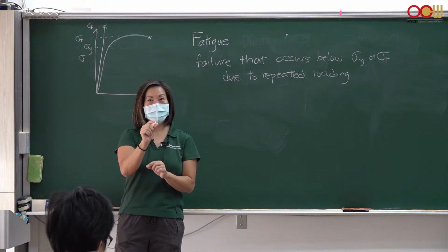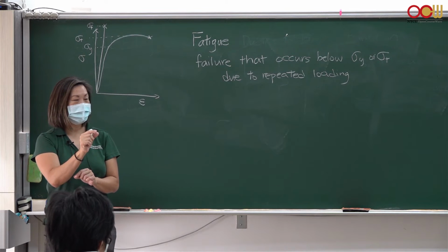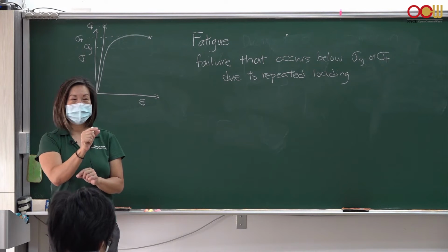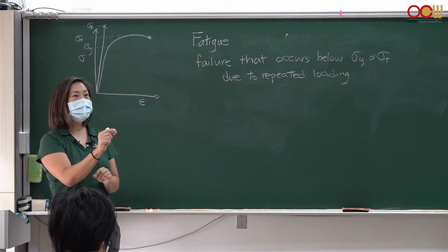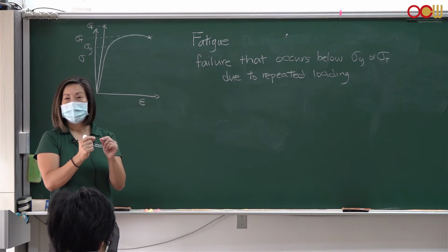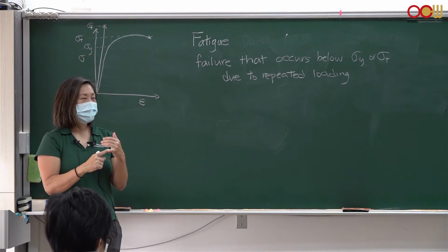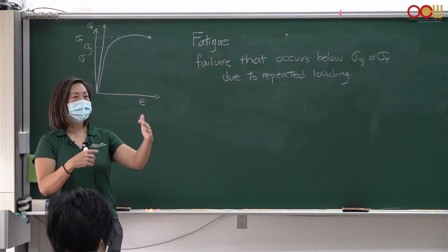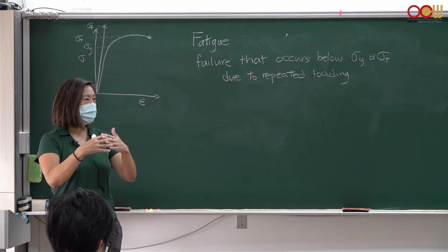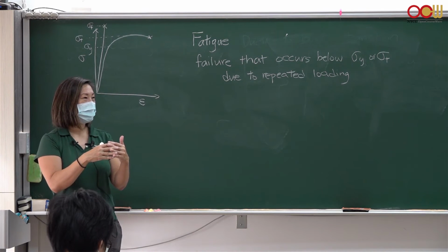So dislocation, there must be, you're creating or moving dislocations within the paper clip part that's bending. Okay, so that's how it's bending. You're creating dislocation movement, slip, okay, in that area. You're creating more and more dislocations in there as you bend it more and more. That's also called cold working, right? You're creating more dislocations. Those dislocations eventually interfere with one another, so it becomes more difficult for slip to occur.